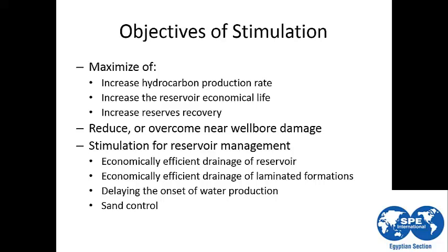If we have a low reservoir pressure zone and a high reservoir pressure zone, we can reduce the drawdown against the low pressure zone and allow it to produce, delaying unwanted water production by reducing the drawdown. Sand control is also achieved by reducing the drawdown across the perforation. This will control the sand production.